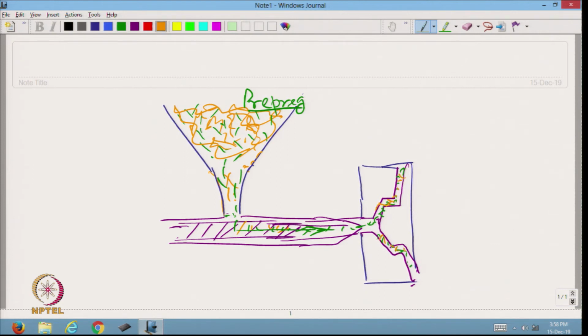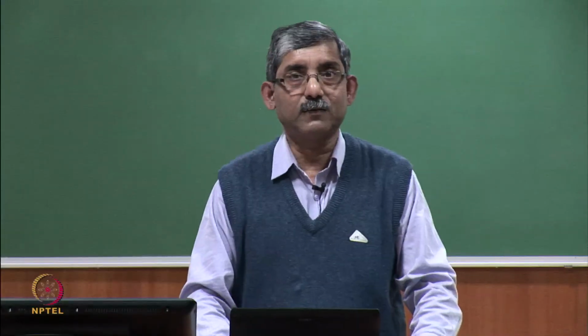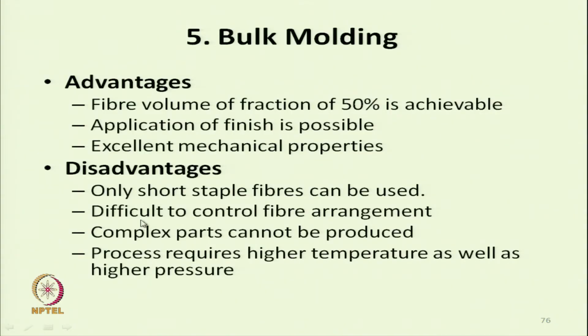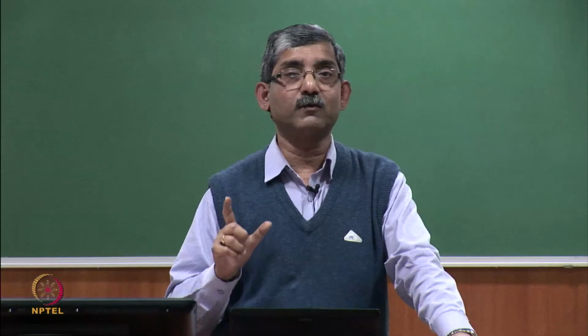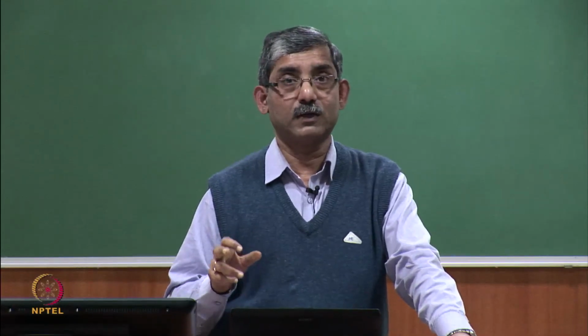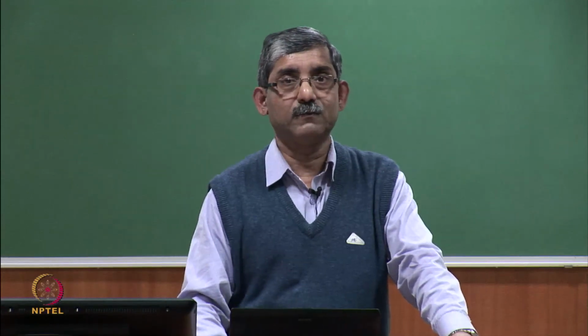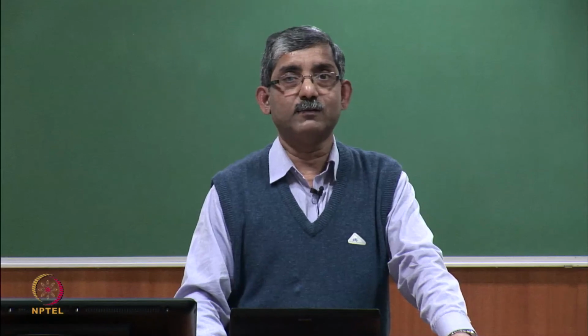And ultimately this will form the required composite. Here the chopped fibers and the resin are mixed. So, only short staple fibers can be used, as has already been mentioned. Continuous filament or long fibers we cannot use, because if we try to use even staple fiber with longer fiber length, then proper mixing is not possible. So, fiber arrangement cannot be controlled,